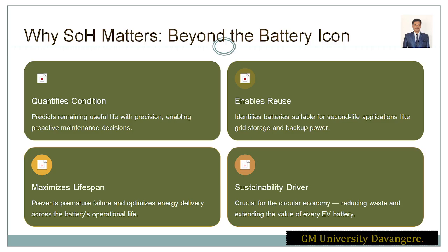So here we can say, if we take the example of 30 kWh as the battery rating, the SOH is around 75%, right? When you multiply 30 kWh by 0.75, it comes to around 22.5 kWh. That is the leftover, right? So that is how we can decide the condition of the batteries. This is how the SOH can be decided, and it plays a very important role in EV batteries.